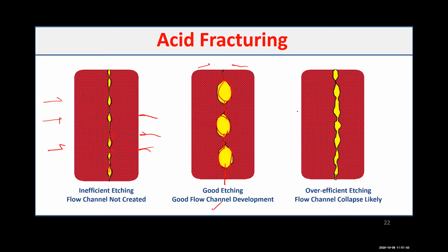The other side of the acid fracturing: if you pump too much acid and actually etch all the surface, if you over-etch it, what will happen? You will end up again with a condition similar to insufficient etching. When it's closed, you're creating too many opening areas, and when the two pieces of the frac close onto each other, it will end us with a very poor conductivity, and the amount of conductivity that you will